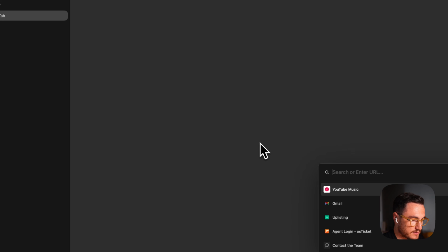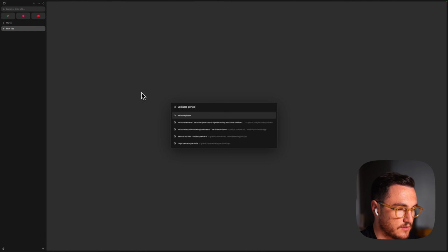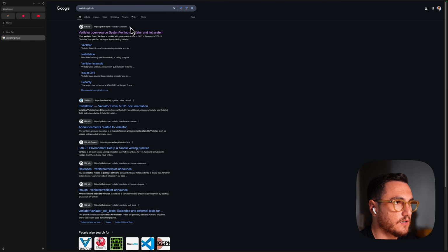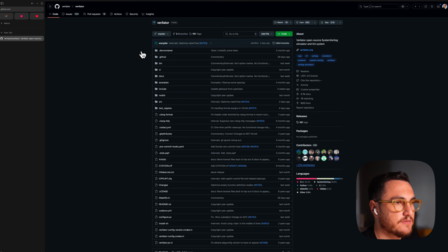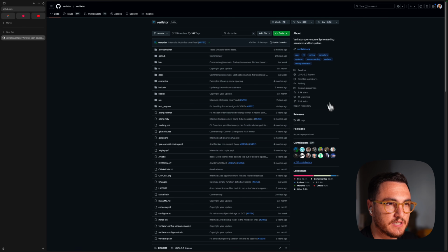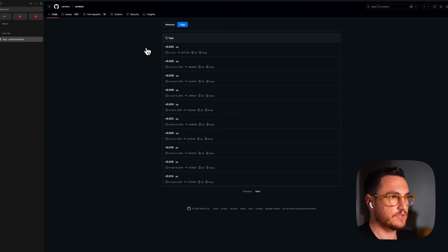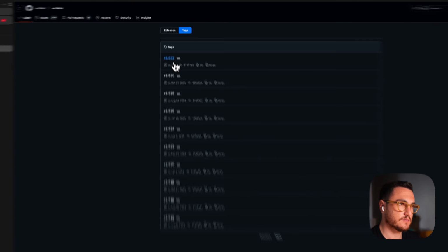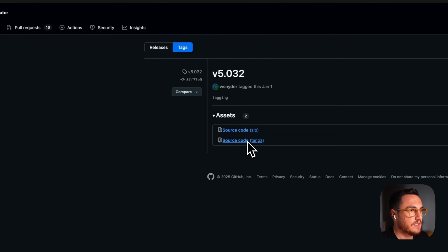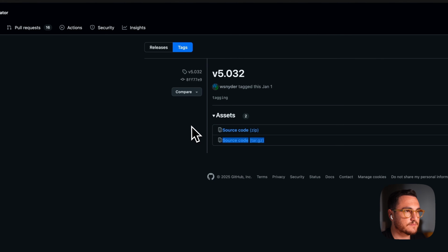So let's search for the Verilator repository, which is hosted on GitHub. Let's go here, in releases, and as of shooting this video, the latest release is 5.32, so let's go with that. Let's right click on the tar.gz file and copy the link address.